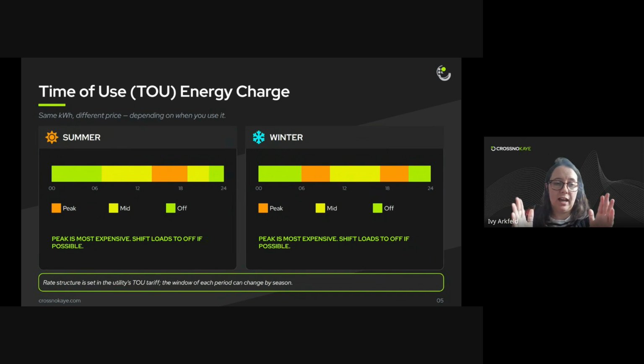Well, this is looking at what was the max demand set during your time of use period, but then also your maximum during the month. So that's another way you can be exposed. This is very typical for a California site to be exposed to something like that. So I just wanted to make sure it was understood that this isn't just energy, this is also peak demand.